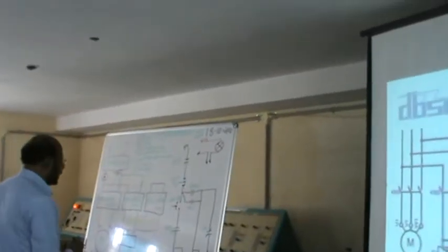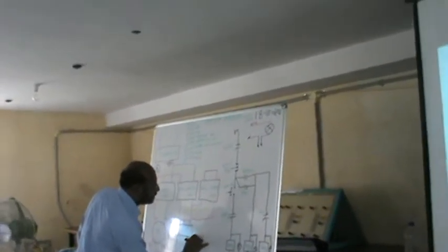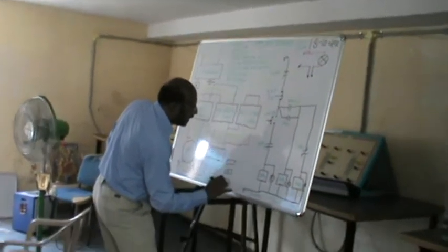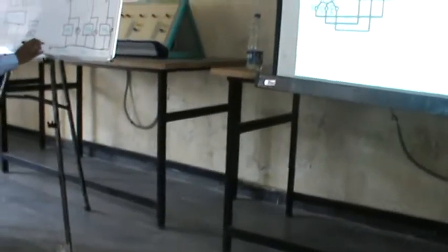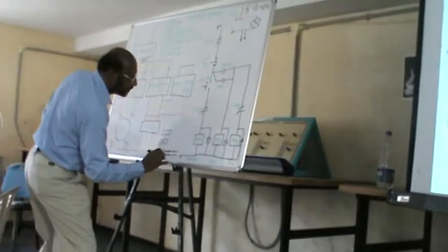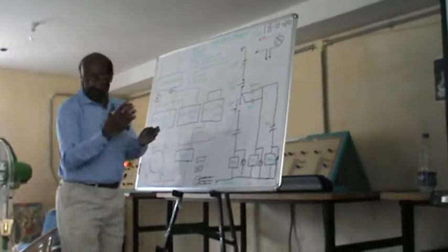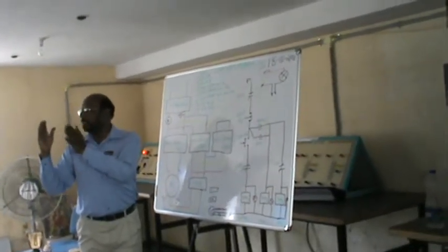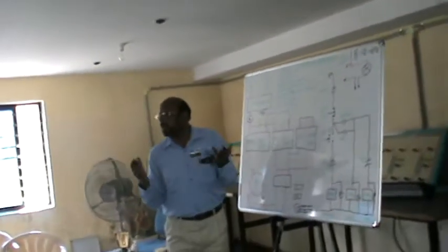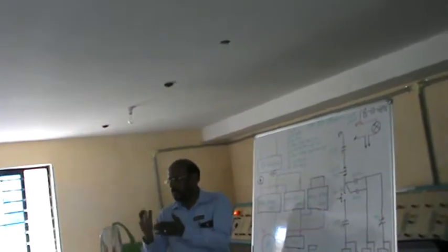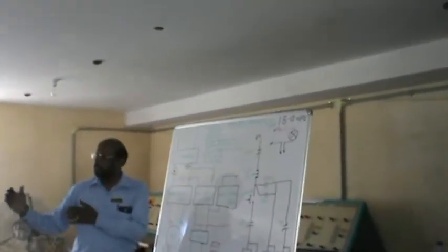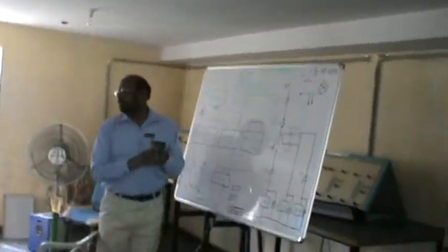In the slip-ring starter, I will just explain. Your MCB, contactor, and motor will be there. And in a slip-ring motor, there will be a winding in the rotor also. Step by step, we remove the resistance. The rotor is connected through external resistance, in 3 steps, because in some cases 2 steps are not sufficient. First step, second step, then the motor runs at full speed. Then 3-step is also there, 4-step, 5-step, 6-step. Whatever smoothness you want, you can have it in the slip-ring starter.